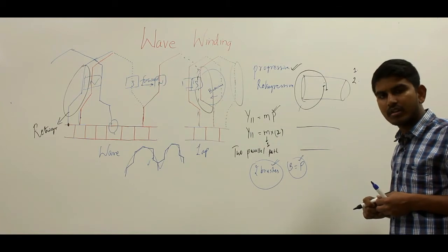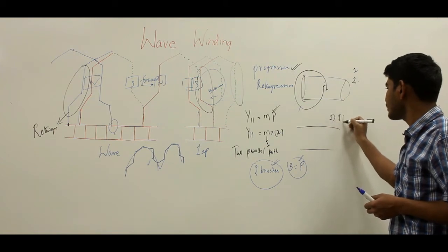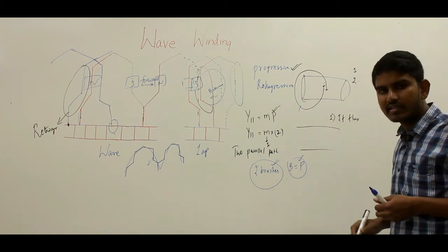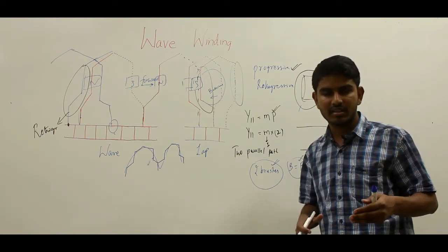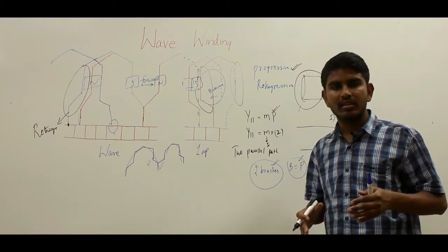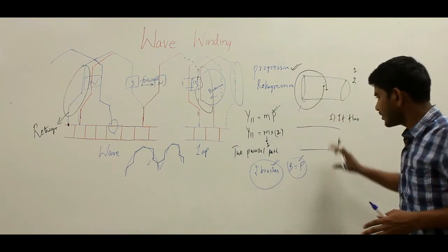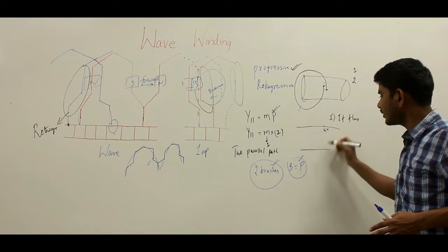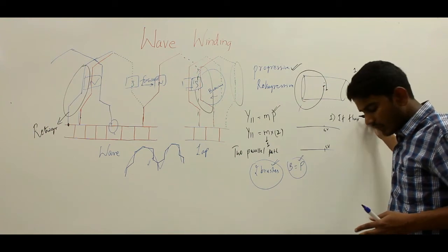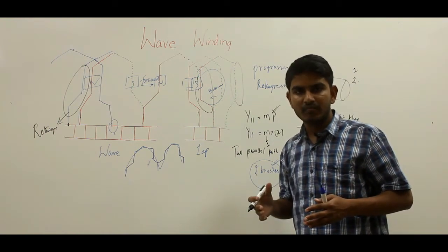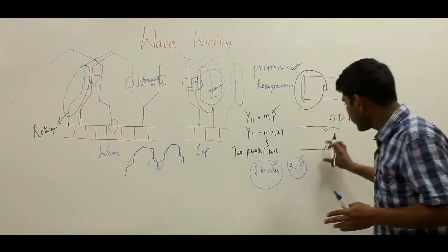as there are two parallel paths and they are distributed uniformly, let me say the flux produced by the poles is not exactly equal for all poles, one pole is producing some more flux, one pole is producing less flux. When they have unequal fluxes, the EMF in the parallel paths would normally differ. But here, if there is 5 volts here, there will also be 5 volts here, irrespective of the unequal fluxes, because whenever there are differences in the flux or differences in the induced EMF, it will affect both the parallel paths similarly.